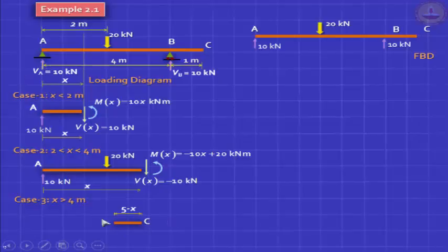So when you come from here to here, this is 5 minus X. But there's no load on this section, and so there's no shear force. Now shear force should be drawn up when you cut the section. When you move from the right, it's pointing up and the sagging moment is 0. So this is obvious. You need not draw this because it's so obvious.